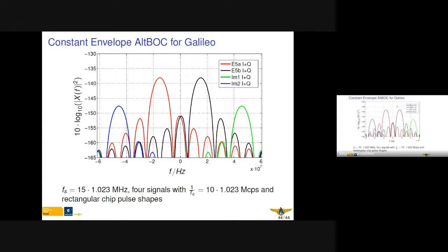If you look at the spectral analysis, maybe in some papers of measurements of the spectrum coming from the signal, you will notice that these side lobes of the intermodulation products are sometimes not visible or very much degraded. This is because after the amplifier on the payload on the satellite, they also have an output filter.